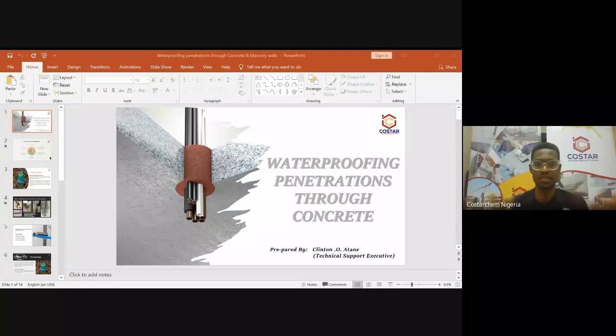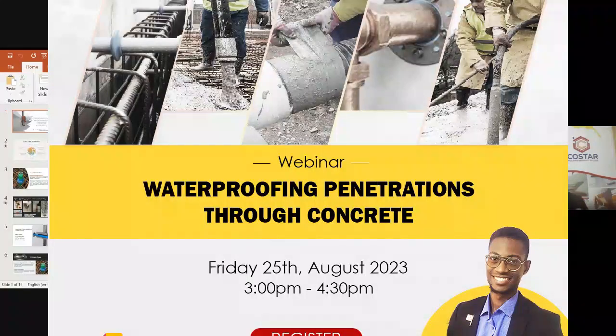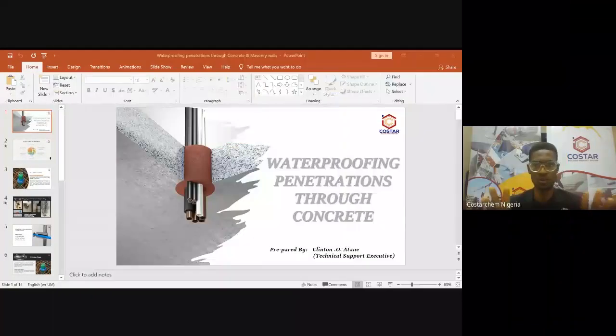This is what you can actually see on my screen. Now you will see diverse discoloration. You would also see spalling. You also observe even corrosion, okay, and general water seepage. All these are very undesirable and affect the aesthetics of your building, of your concrete, okay.